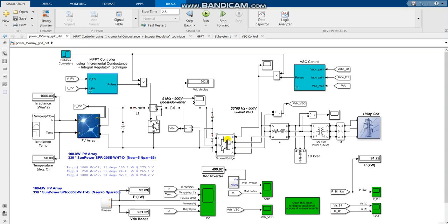Now, with it using IGBTs, one advantageous thing about that is that you can control both the on and off time for when the IGBT operates. This is more advantageous than using a thyristor, which you can only control the on time. One useful thing about this is that it could allow for voltage amplitude modulation.